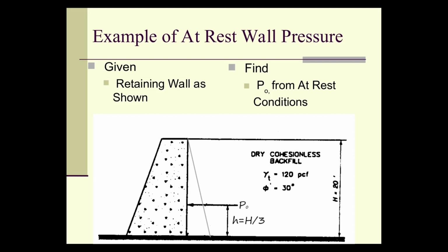We're going to be dealing in resultants, lots of resultants. Geotech engineers love resultants. Traditionally, in hand calculations, they're the way we eliminate a lot of the problems that come up using distributed forces. And when we can use them, we do. In some cases the results are different, but overall, if we want to know the total force the soil exerts against that wall, the resultant is the answer we're looking for.